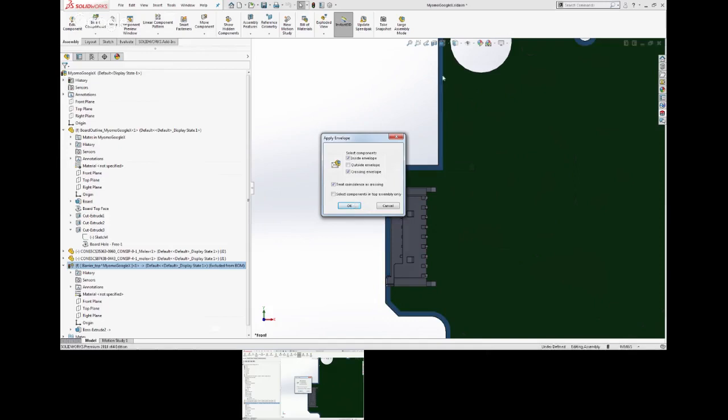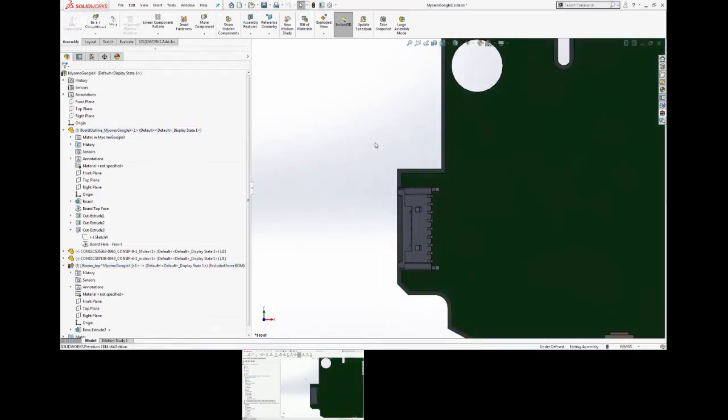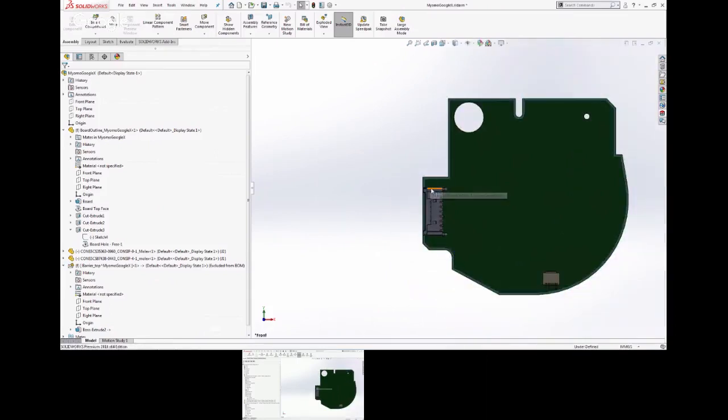Now this envelope, which I created in SolidWorks Mechanical, is used as a placement barrier on the XY, and I can repeat the same thing to create a placement barrier for components on the Z. If there is a height restriction when I bring in the enclosure, some section must have low profile parts. I can define the same thing with any polygonal shape: create it, give it some extrusion, and that will get transported over to the electrical.